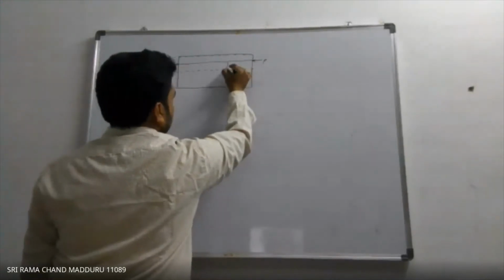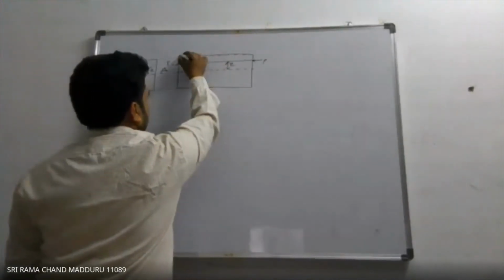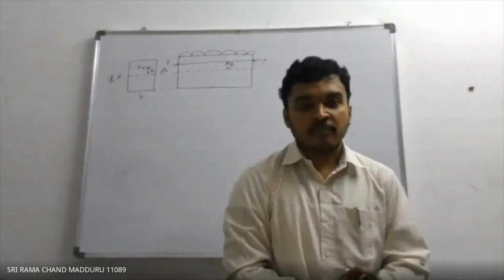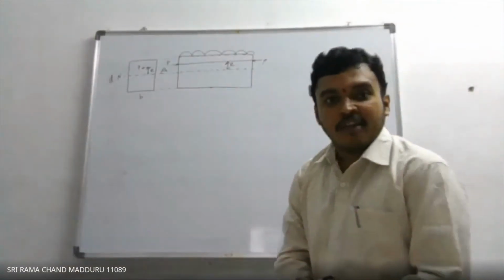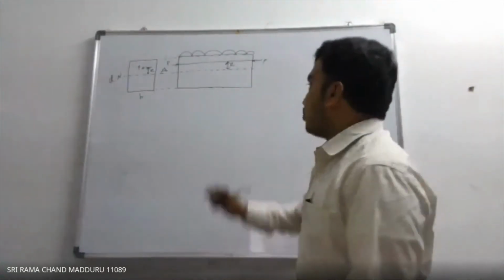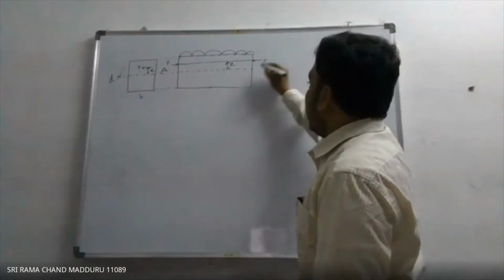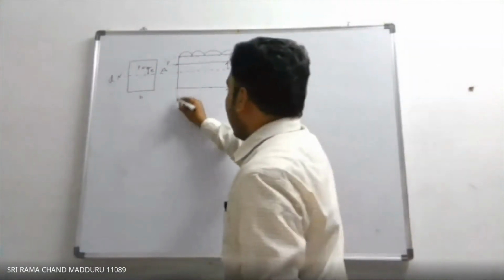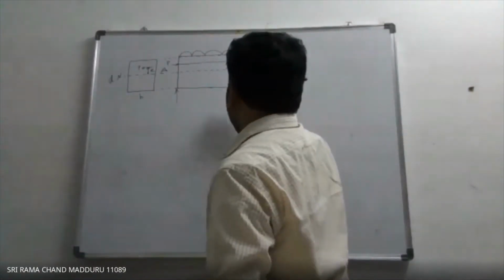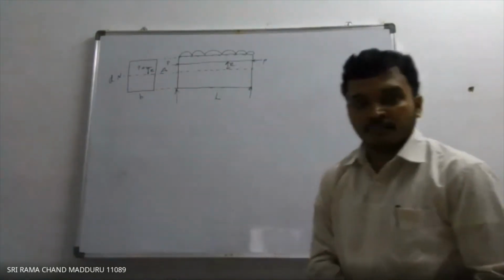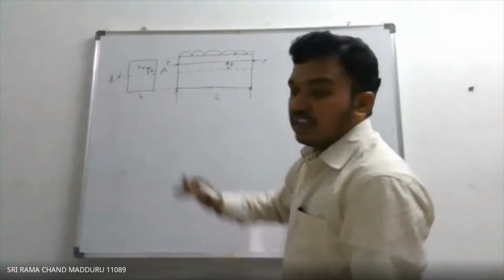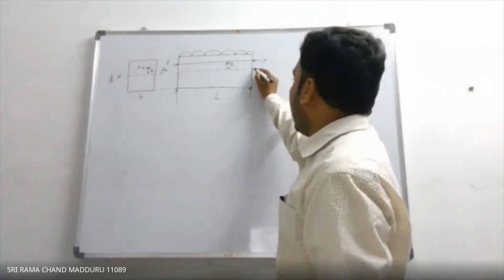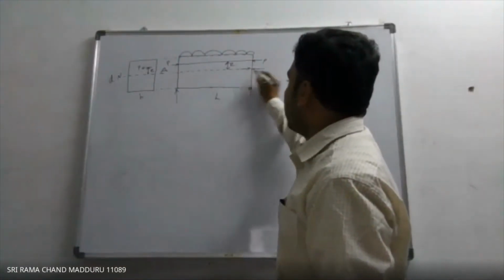So now you observe this one. This is above the neutral axis. Now the beam is also subjected to loading. This is the condition. Now for this condition, what we need to do? Here I will once again write down the equivalent beam. I am again taking the simply supported beam of span L. Now how can we change this beam to an equivalent beam? Apply equal and opposite forces at the neutral axis.